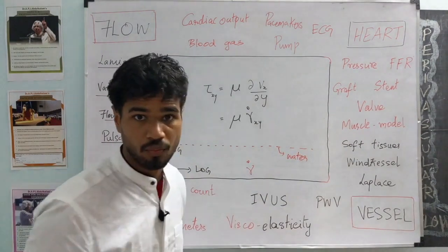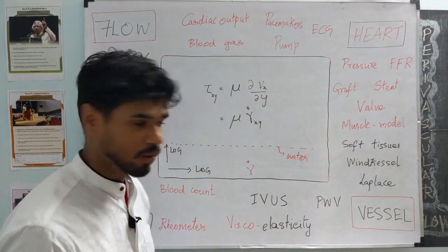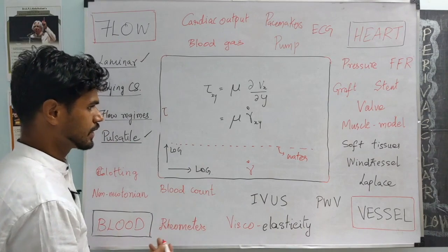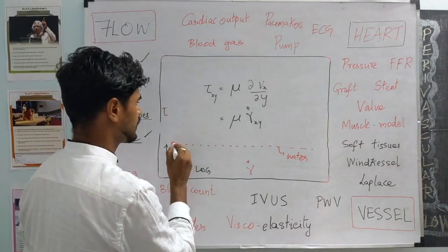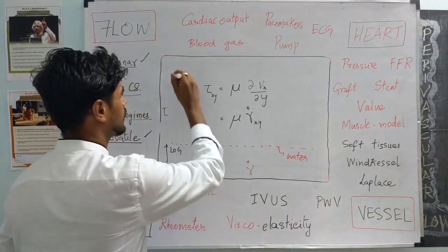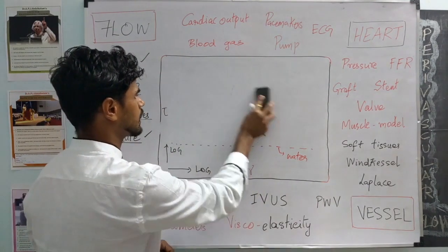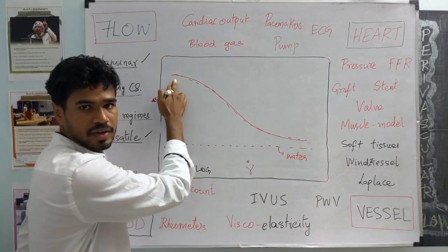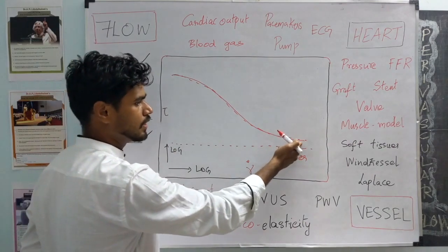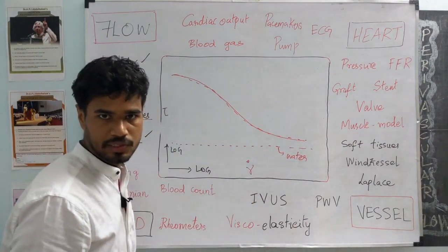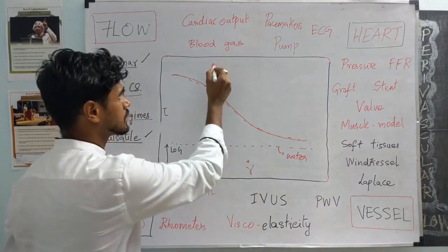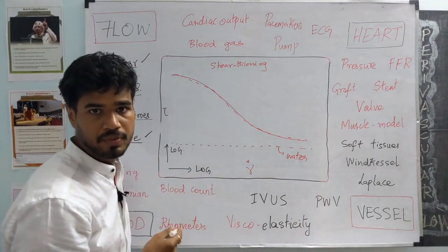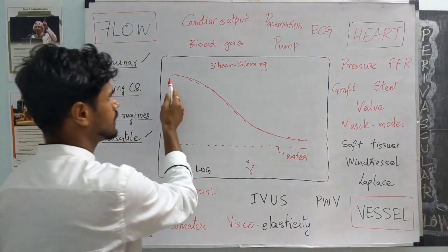But blood is not like water, blood is more like sambar, with all those cells and proteins in it. So based on that, the actual viscosity of blood is going to depend on the shear rate. And the actual dependence would look something like this. At very low shear rates, we have very high viscosity, and at very high shear rates, we have lower viscosities. This is what is known as a shear thinning liquid, and there are various mathematical models to approximate this behavior.